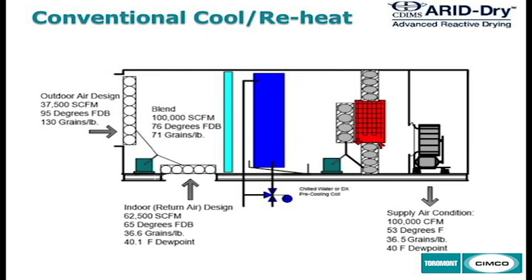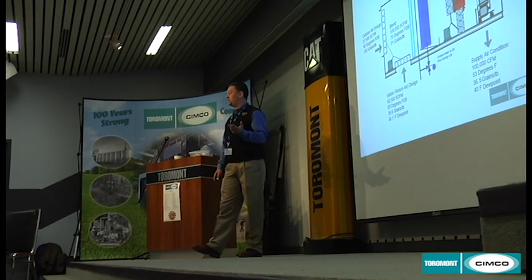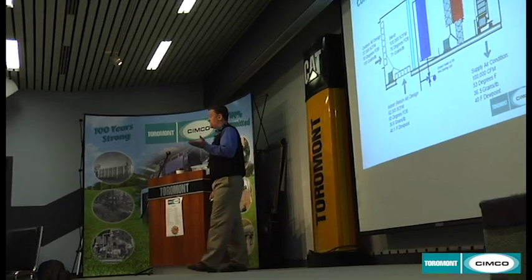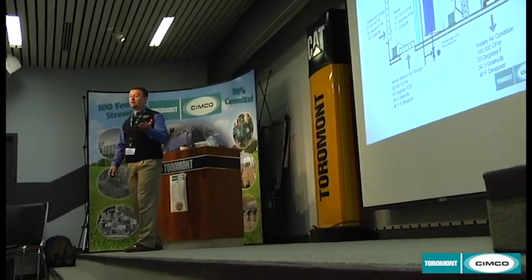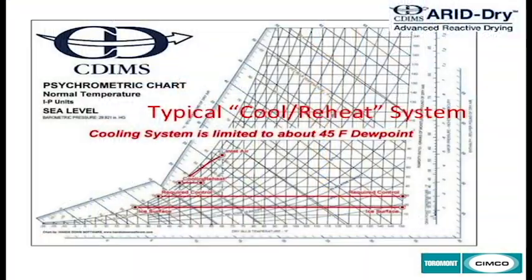So if we said that we needed to achieve a 35-degree dew point to get rid of all of those problems, and we're delivering a 40-degree dew point as a control, we're never going to get to set point. So in that building we can really only reasonably expect to hold maybe a 50, 55-degree dew point, which is higher than what we said is going to be acceptable for you and your customers, and it's going to negatively impact your operating costs.